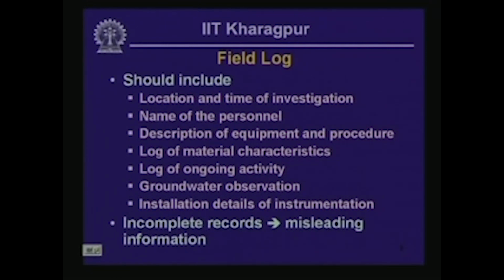Then there should be groundwater observation, whether the water flow, or water used in the progress of the drill hole that is lost within a cavity, that also should be mentioned here, water loss.